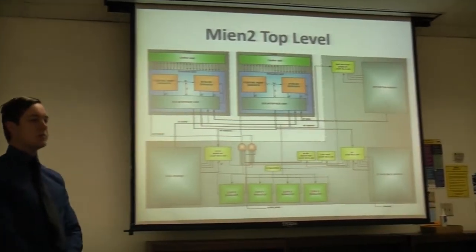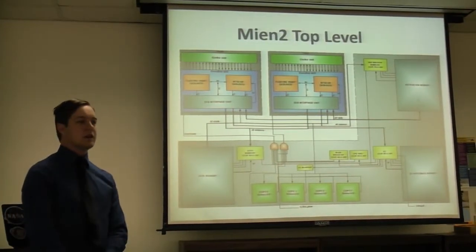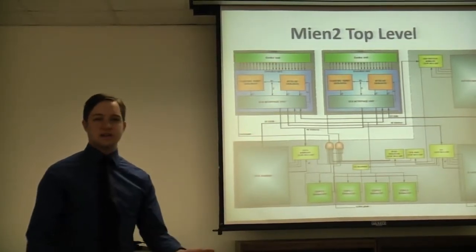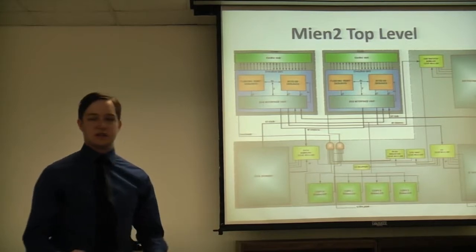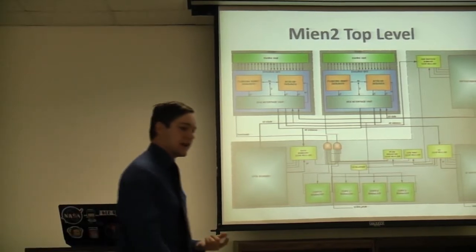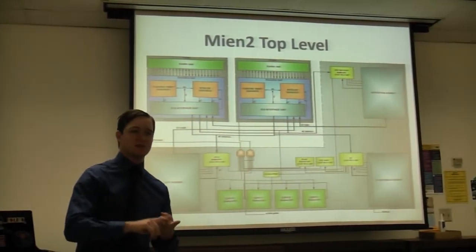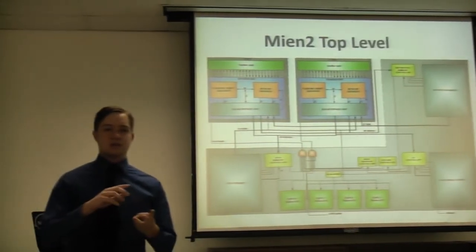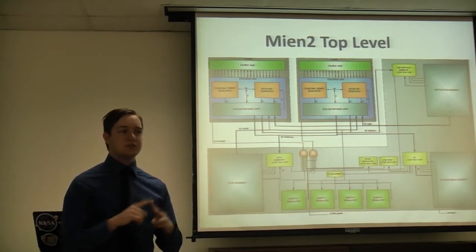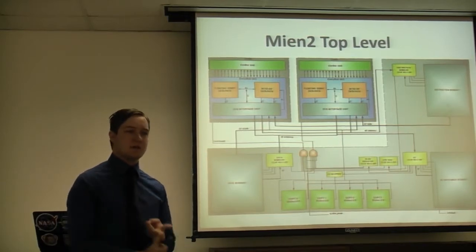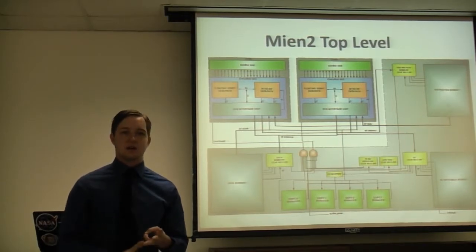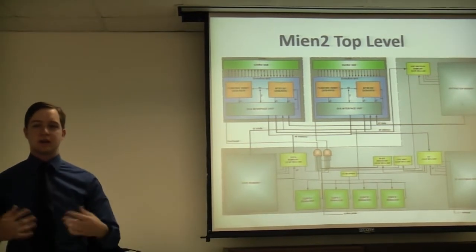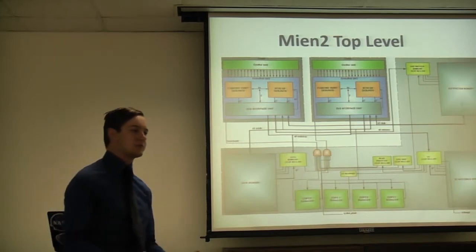This is version 2 because it's a dual core with enhancements for support up to 4 cores. Why we say 3 cores is the theoretical maximum: if each core is running in its most efficient state, which is fetch, decode, execute, the instruction memory is always being read, data memory is always being read, and they are always executing. So core 4, without caching, will never be able to access the data because it's the lowest priority.